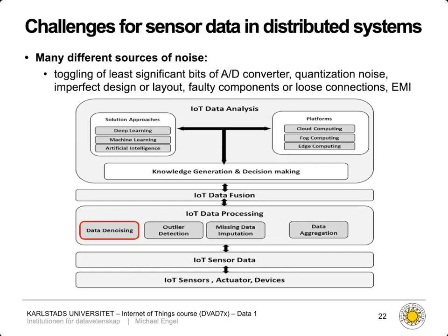So how do we get noise into the signal at first? Now, first, the problem is that AD converters aren't perfect, so they're temperature dependent, and especially the least significant bit is just a very small voltage which can toggle there. So maybe these bits can toggle between 0 and 1, even if your voltage is constant, because it's just on the border somewhere. You can have what's called quantization noise. We'll discuss this in a bit more detail.